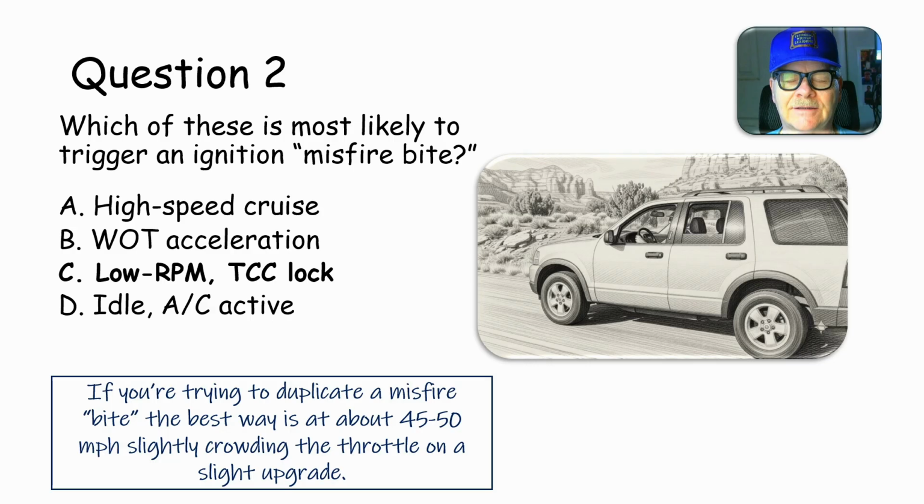So the shop foreman rode with him, and this guy was tacking this thing out to about 6,000 RPM, and it was cutting out with him burying the throttle. The shop foreman said it sounded like he was trying to blow the engine up. He brings it back in, and the older spark plug wires went through a boot down into the tower socket in the distributor cap. The guy had replaced his own spark plug wires, and one of them was stuck down in there where you couldn't see the terminal, but it wasn't pushed all the way down so that it was snapped into its socket.